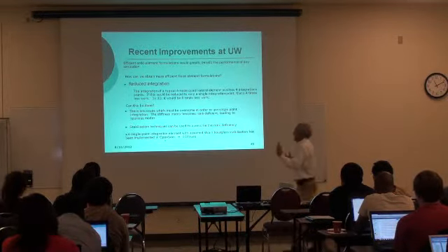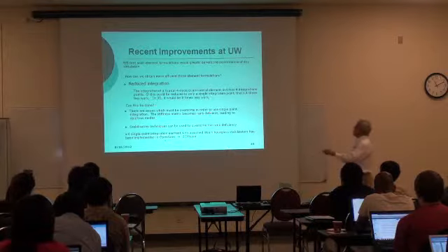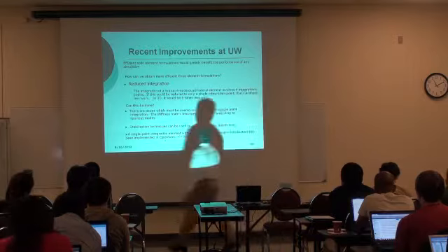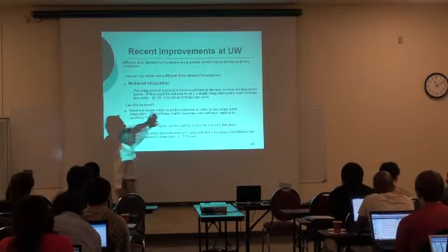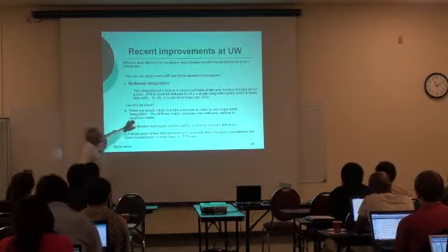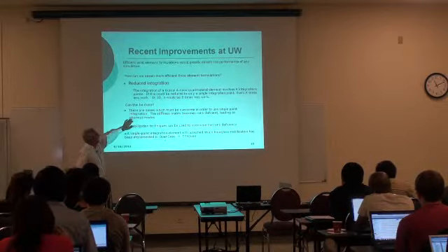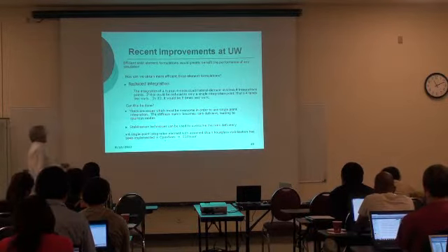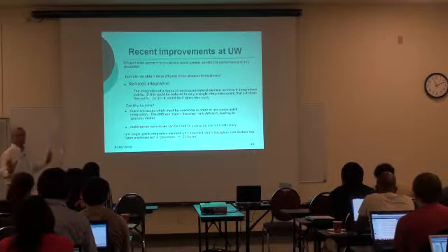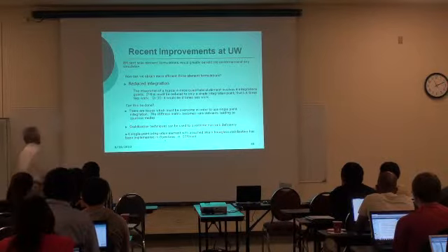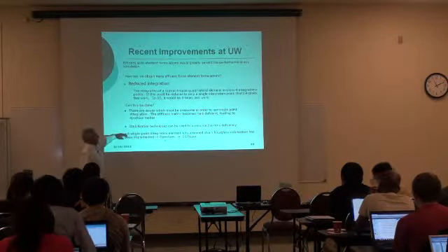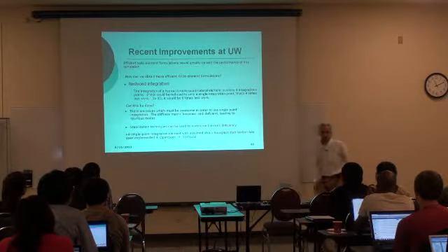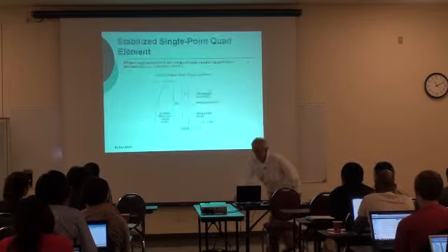Can that be done? Well, the problem is that there are issues that must be overcome when you use a single point. In particular, the stiffness matrix becomes rank deficient. That's a problem, and it leads to what are called hourglass spurious modes. So you have to deal with that problem first. Stabilization techniques can be used to overcome this rank deficiency, and we used that. A single point integration element with an assumed strain hourglass stabilization was implemented in OpenSees, and you can use that nowadays.